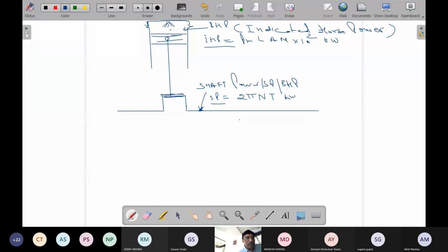So first thing we are saying, BHP over... let me write in terms of efficiency only so that there is no confusion. So I am writing eta and I am writing here mechanical efficiency, MEC. Short form is MEC, is equal to BHP over IHP into 100. This is equation number 1. This is the formula we have discussed so far, mechanical efficiency.